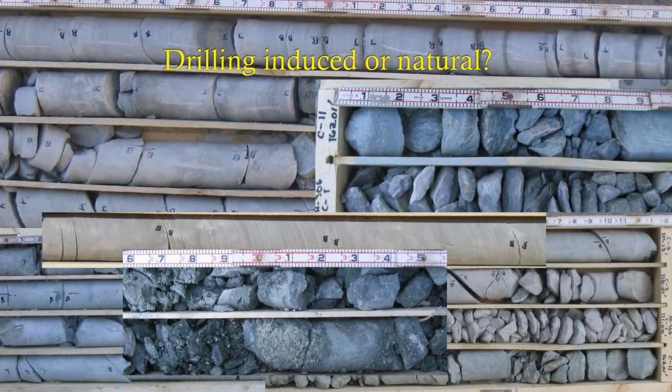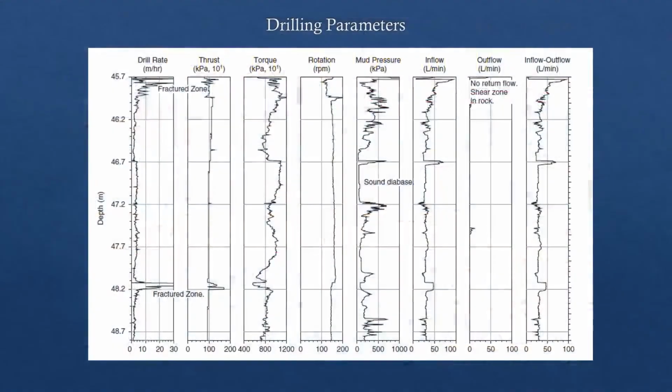Here's a slide showing various sections of core boxes. You can see you can get all kinds of stuff in there. Well, what do you do with this when you're trying to do your design? Are you looking at a joint, or are you looking at a break that was induced by the driller? So what is the real RQD in there? So that's what we looked at.